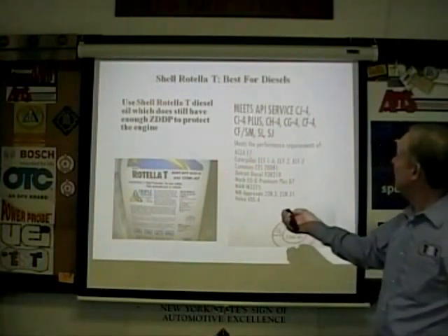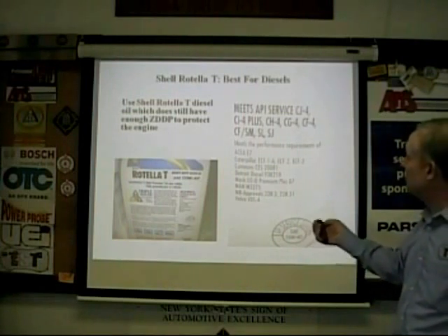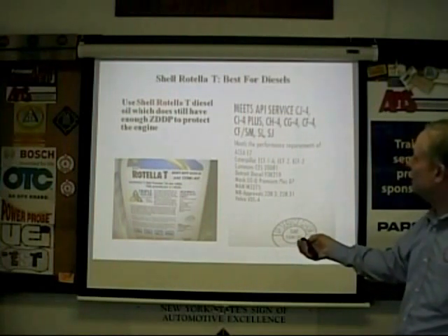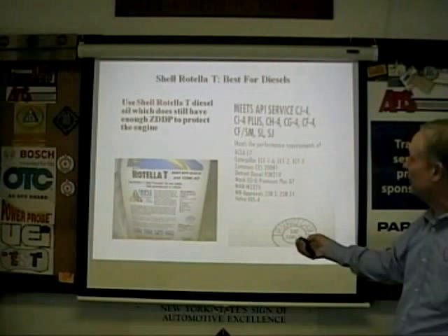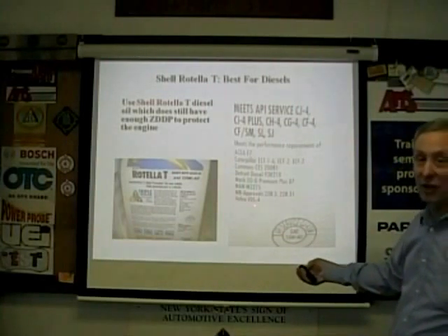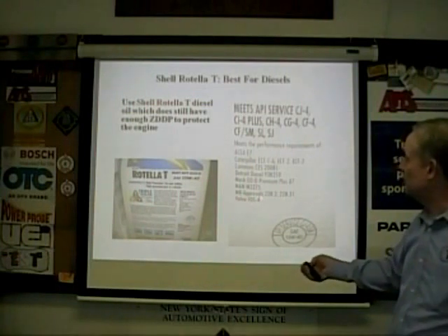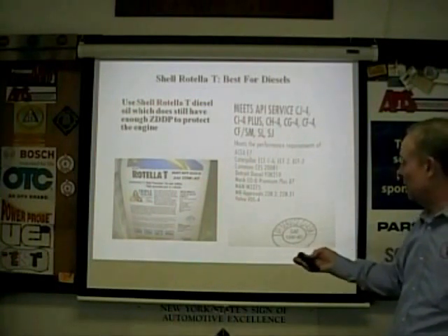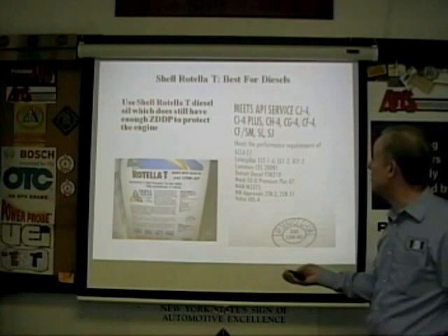All right. Again, make sure it meets the specs. Look at that, ACEA E7, Caterpillar. This is obviously for heavy equipment, but notice, Volvo. We didn't mention Volvo before, but they have their own specs. Mercedes has their own specs. You've got to make sure it meets your spec for whatever you're working on.